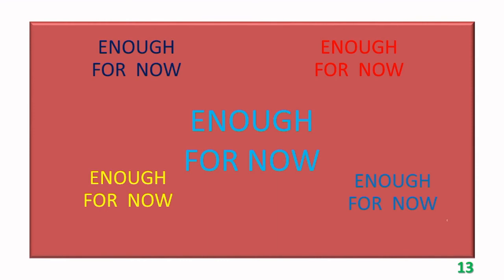With this, we come to an end of the session. To recollect, in this session, we described the direct coupling scheme and then the impact of multi-stage design on bandwidth, on lower cutoff frequency and upper cutoff frequency.